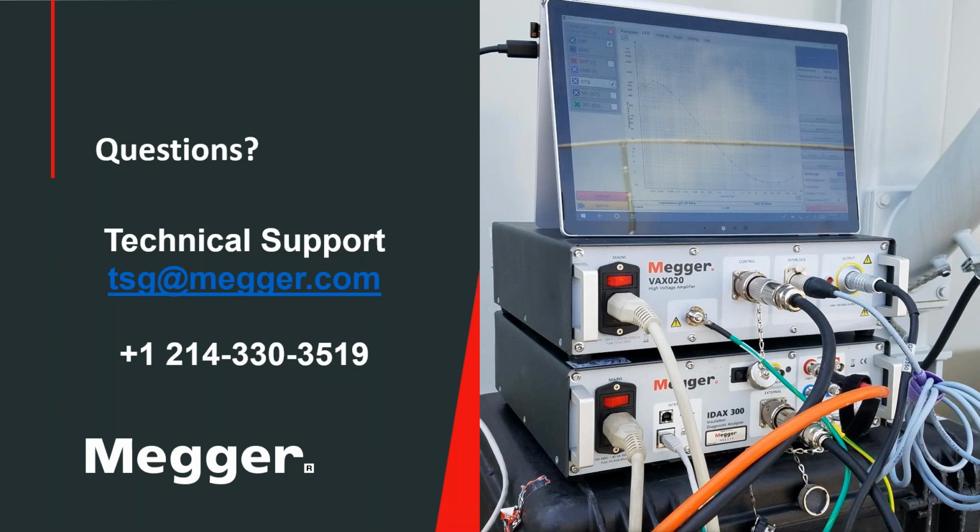All right, thank you. While I have you, the next question is also directed to you. For DFR, some people think more voltage is better for the test, but how does voltage affect the measurement, and what is the recommendation for DFR test voltages? Okay, so basically, under normal conditions, doing your typical UST test to determine the moisture in the power transformer, where you have a big capacitance, the only thing that you need is 140 volts RMS.